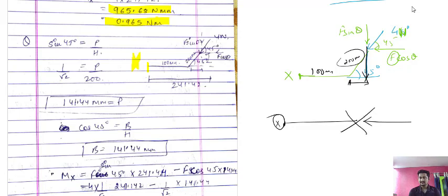But in this case this force is away from this line of action and has a perpendicular distance in reference to this point. As it has a perpendicular distance with reference to this point, it will be producing a moment this way. As the point is downward, it will be producing an anti-clockwise moment and this will be producing a clockwise moment.